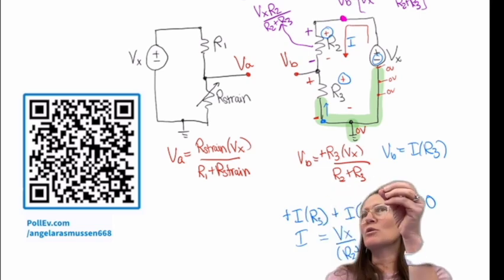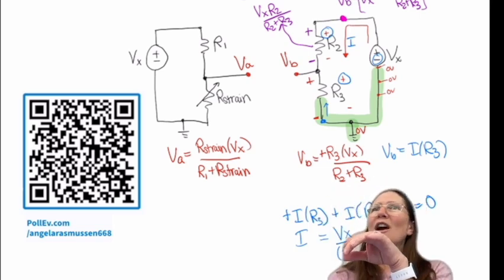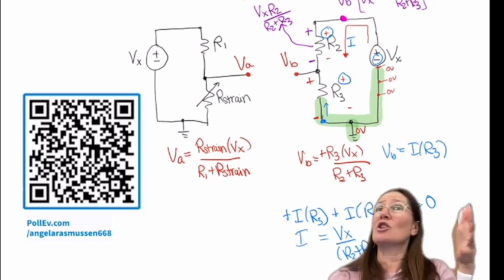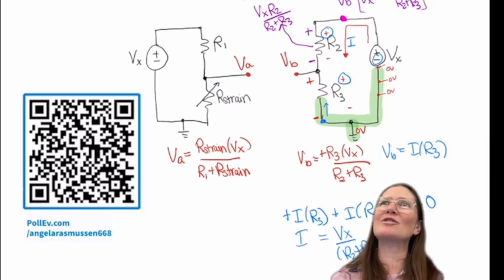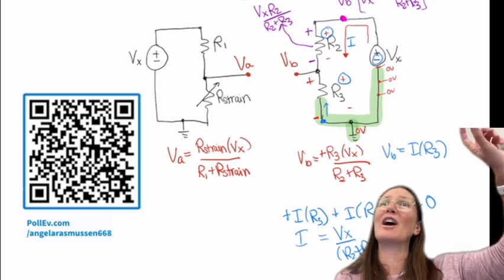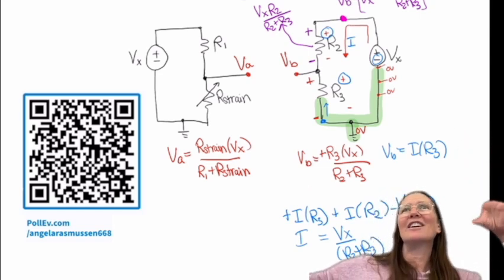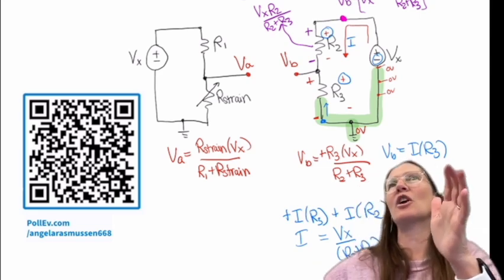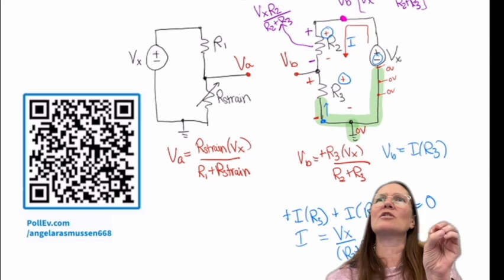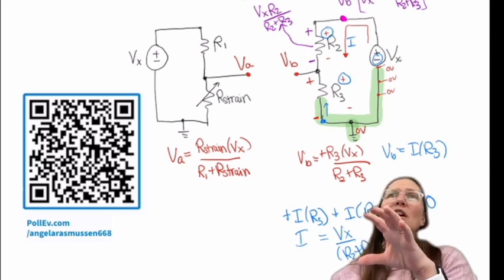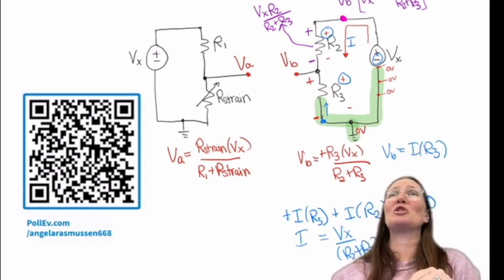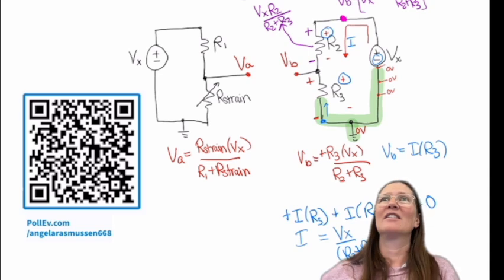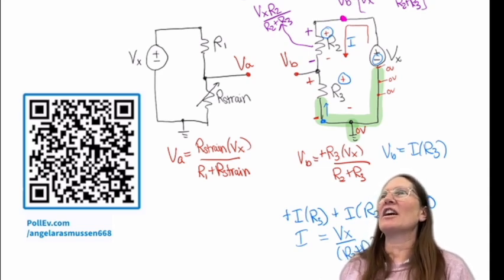The hard thing though with the ground is, I usually like to start at ground because it can get confusing, because grounds can be connected somewhere else. It's really easy to make an error of going through another pathway and you've actually created 2 pathways and not realized it because of that ground. So I typically recommend starting at ground, but theoretically you could start anywhere as long as you get back to the same spot and you ignore the ground. Okay, other questions?